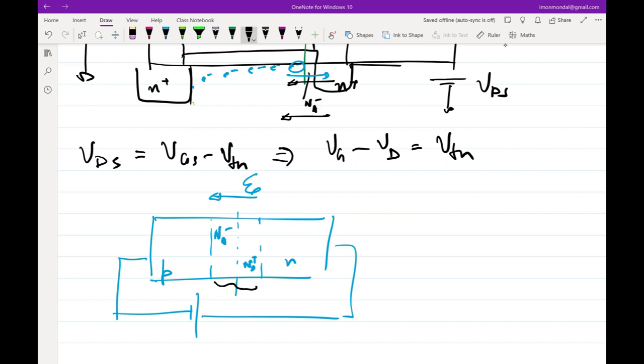The electrons might be generated by thermal generation, or because you have dropped some electrons into the depletion region. But let's assume somehow the electrons have made it to the depletion region. Then the electrons will be swept by the electric field in this direction. These electrons will flow in this direction, which means there will be a current flow. And that was one of the genesis of the reverse saturation current, right?